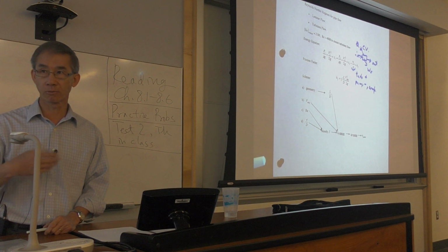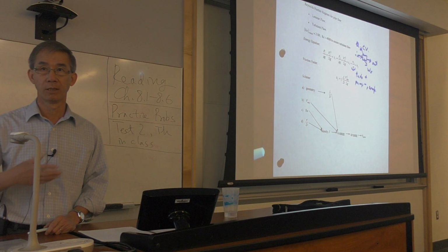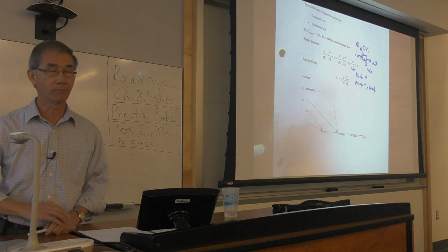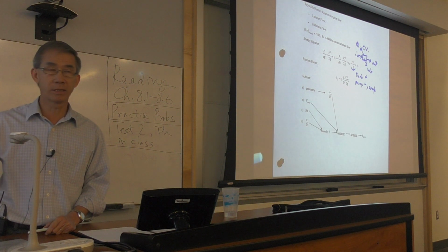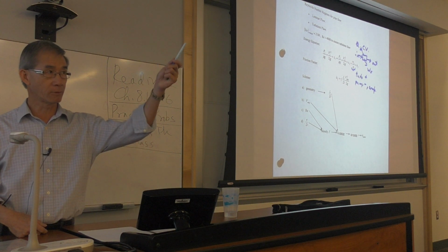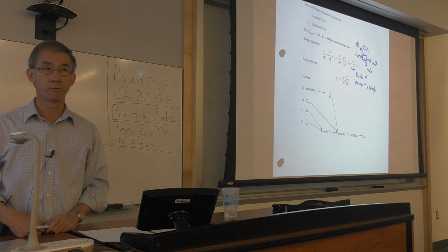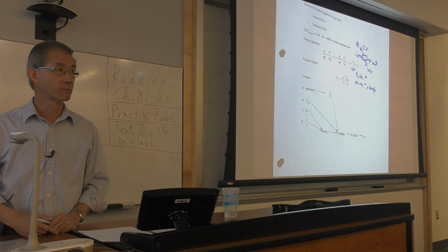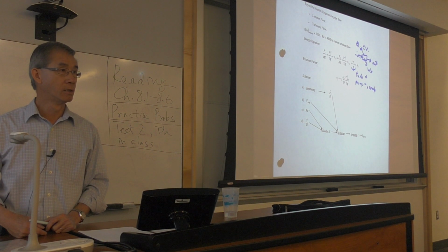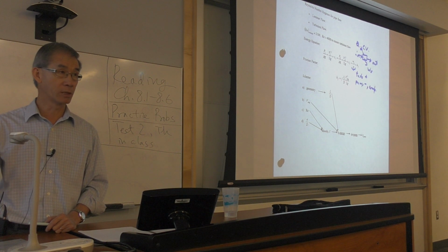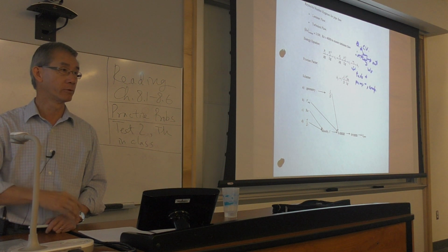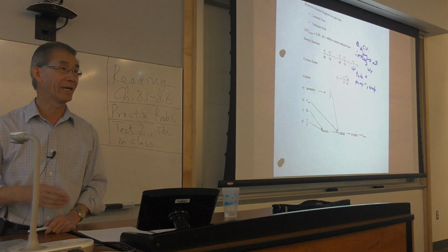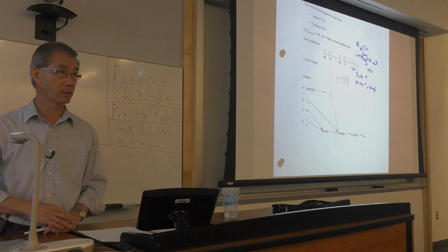So that's obviously work added from electricity to the fluid. And so compressor is the same. To run a compressor by itself, you have to have a huge DC motor. To test a fan blade out in the edge of the hallway, it may take about 1 megawatt of power. You have to put a huge DC motor and provide the power to run it. And that power is being transferred from the fan blade of the compressor to the air that goes through the fluid. So it's work added to the fluid, and hence it's negative.